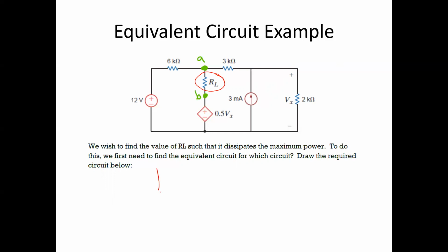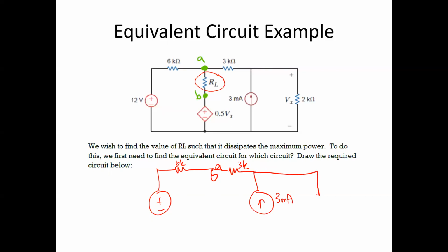And so this first part really only asks you to draw the circuit in its identical form, but by recognizing that you need to find the Thevenin without the load. One of the more common errors that students make, especially if a value is given for this resistance, is to leave that in when in fact you're interested in the Thevenin of everything else.